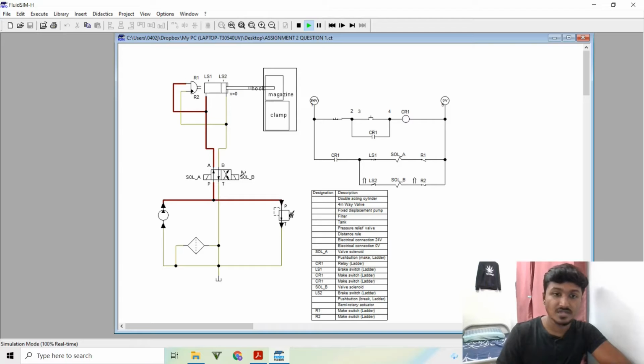After I activate the second solenoid, it will change back. Then the rotary actuator will twist it 90 degrees right here. Then it will hold it, retract it, then drop it. It twisted 90 degrees, and it will hold it, retract it, and then drop it.